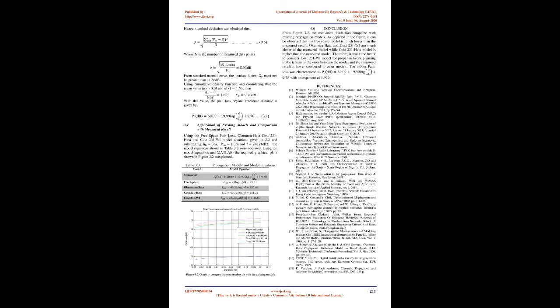3.2 Determination of path loss exponent using linear regression. From Equation 3.4, the path loss exponent was calculated for the outdoor environment within Akwa Ibom State University as 131.13/65.5976 = 1.999. 3.3 Determination of a shadow factor using standard deviation analysis. To compensate for shadow fading, as the terrain is composed of buildings and other structures, the large-scale average path loss was predicted at 50 m as 60.09 + 19.99 log10(50/10) = 74.06. (3.5)